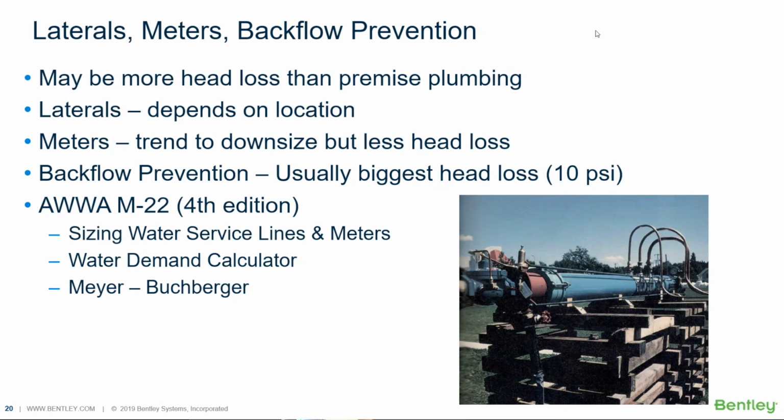So you can't just go from the main and assume what's going on in the water main is what's happening in the building. And this is one of the big questions that comes up when people are designing buildings: what's the pressure in the main? I'm going to use that as a starting point for my model. And this always scares me when somebody asks me that kind of question, because there is no value.